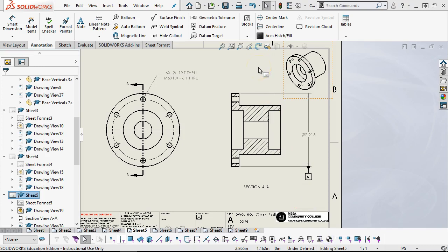All right. So again, maybe not the best use of the surface of profile. We could certainly have a lot more functionality than the outside geometry. For your B datum, then, that primary, the datum simulator would be picking a face, having flatness and parallelism, and then we would need to see if positionally, well, since that's our datum reference, everything comes off of it. The surface of profile kind of reverses that action. So, it applied it. Oh, it applied it to the basic dimension. All right. So I don't need that one. I didn't catch that. All right. So we'll think through the rest of the process on that one, so we can wrap this pass up.